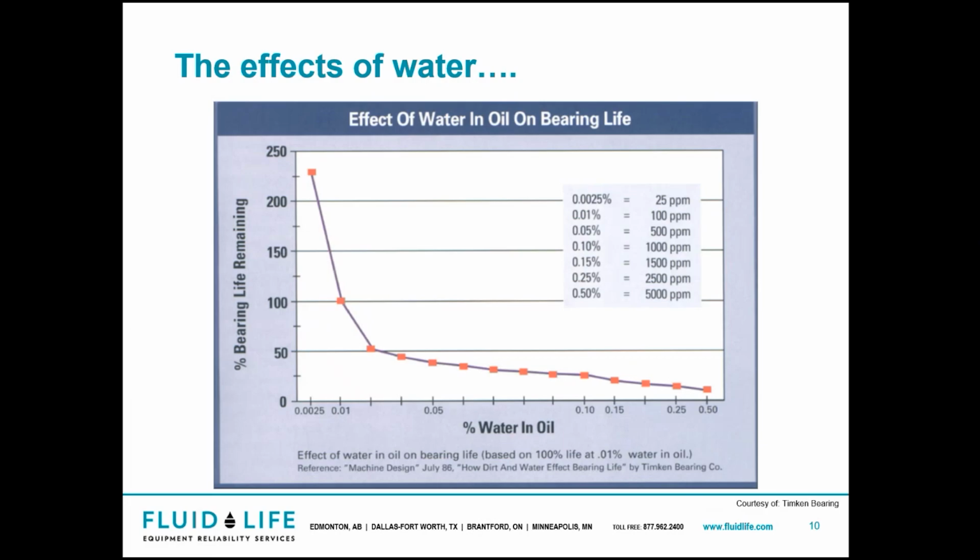Same type of principle goes for water. It's imperative to know how water has a huge effect on our equipment. There are a couple of tests that most oil labs do for testing for water. Now, there's the crackle test. For the crackle test, the oil is basically slapped onto a hot plate, and you look for it to bubble and pop. That is usually only detected at about 150 to 200 parts per million.